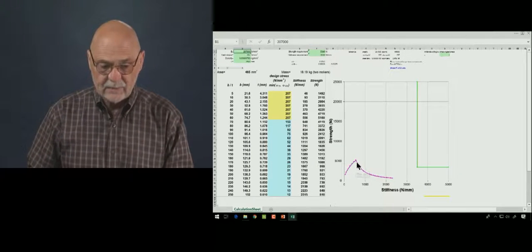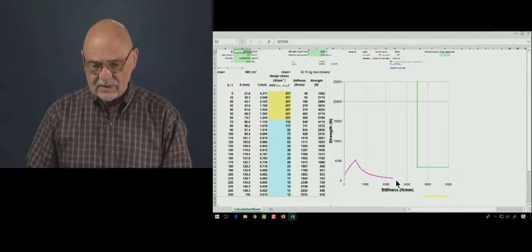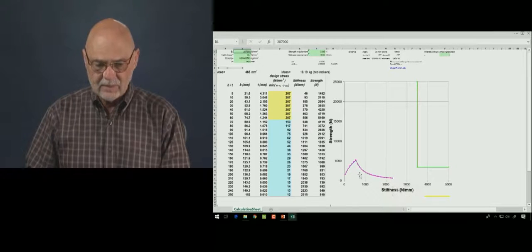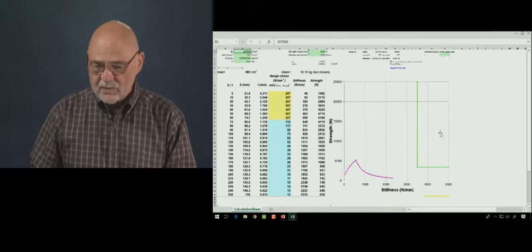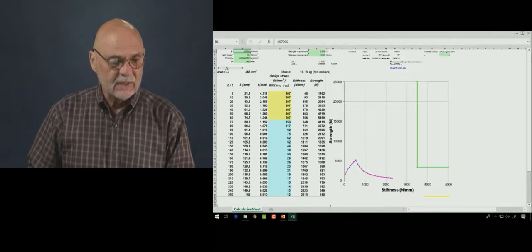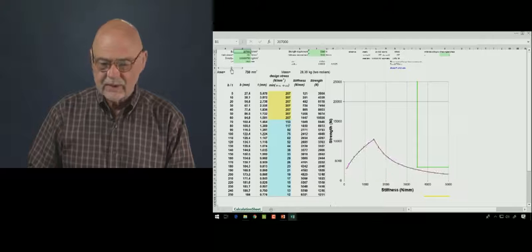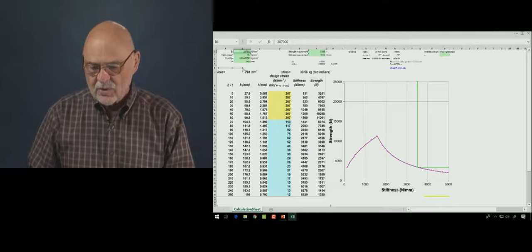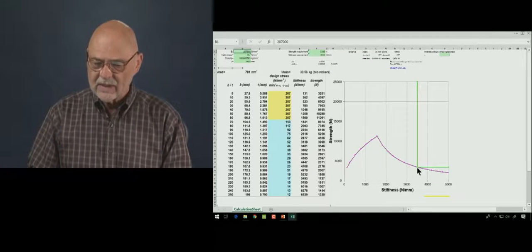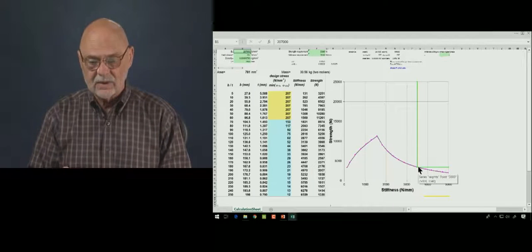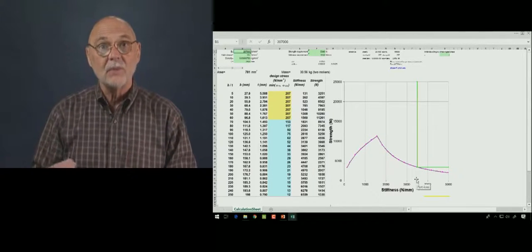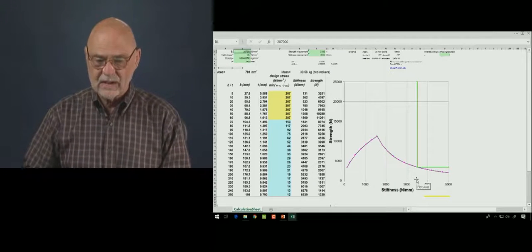And here we have B over T of 60, 70, all the way up to some really pretty high numbers here. But this goes in increments of 10. So again, we're trying to get into this region here. So let's do this quickly here. We're starting to get really close. There. So we have a solution here. We just zipped into this acceptable region for both stiffness and strength. And it's obvious that it's going to be a thin wall design. That's the winner of the contest.